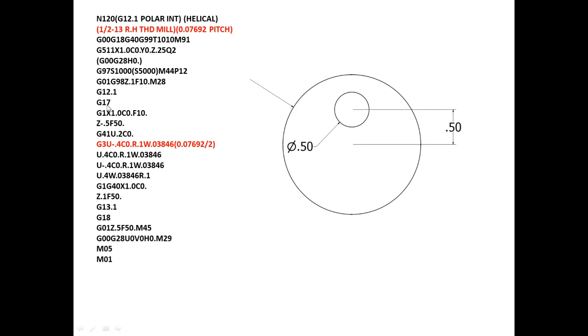Same G17, we will use X and C. And then G1 Z minus 0.5, that's the thread depth. I just go half an inch inside of the hole.